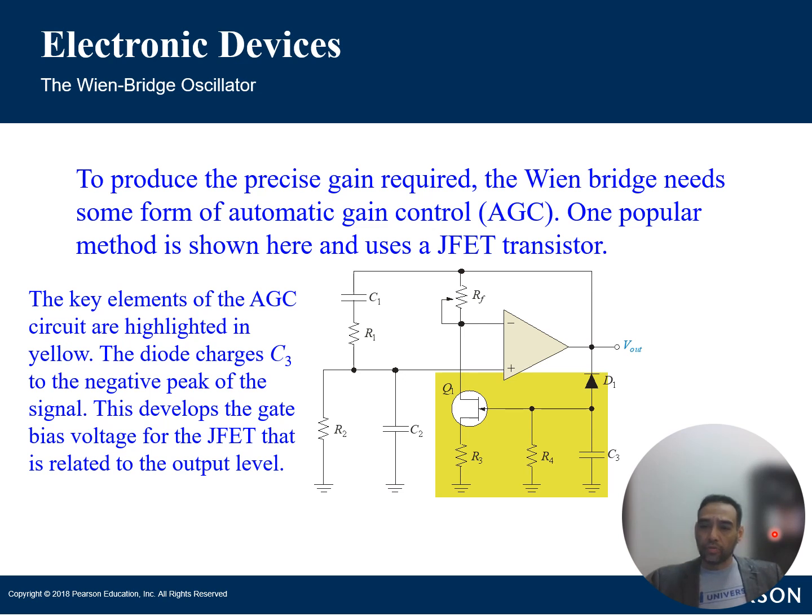The feedback mechanism, this factor of the oscillator. So I said I was going to be hitting each one of these factors as we talk about the different types of oscillators. There's a bridge network. It provides the positive and negative feedback to the amplifier. At some desired oscillation frequency, you can have a phase shift around that loop. Would you try to maintain a zero? Again, theoretically, but ideally no. It's going to lead to some kind of positive feedback.